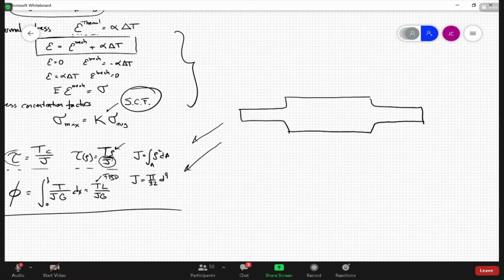You had this and this, right? So of course there's a force here. So when you're designing something, every single point has to survive. You can't just say, oh, I only checked one part. And you don't necessarily know a priori whether the stress situation will be worse at the hole or at the fillet.